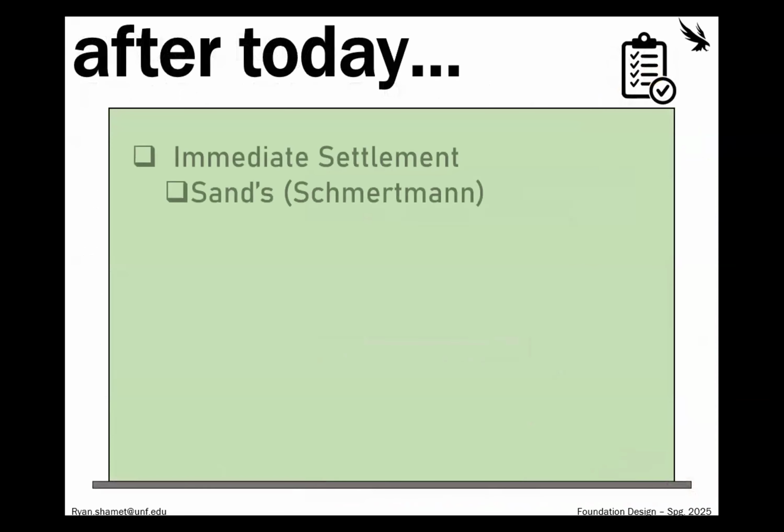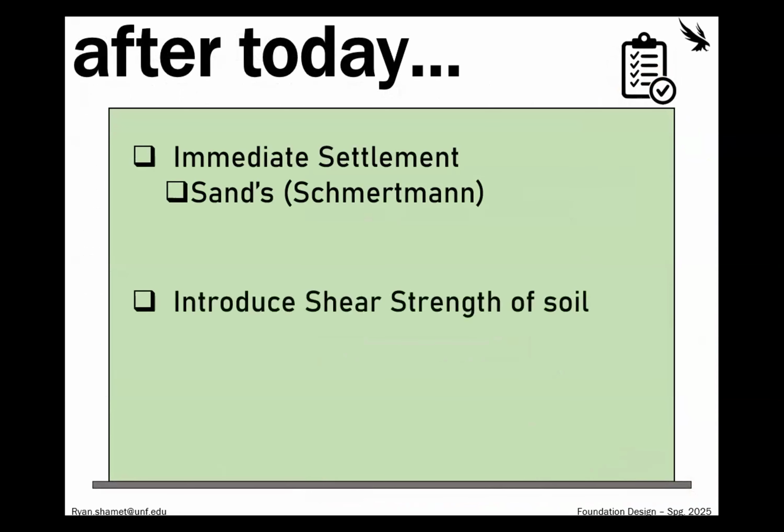All right. So after today, we are going to be talking about immediate settlement or elastic settlement in sands. And then also we're going to be introducing shear strength of soil. And shear strength of soil is one of the most important concepts of foundation design, especially introducing bearing capacity. So when we talk about shear strength of soil, I want you to think like, okay, for concrete, we have compressive strength. For steel, we have bending moments and tensile strength. For soil, we have shear strength. That's the important thing that we design against.